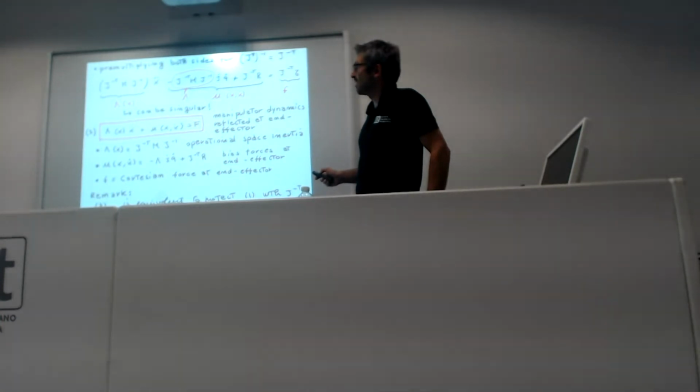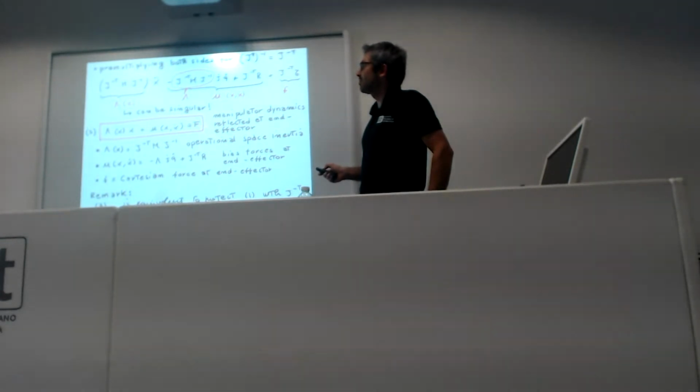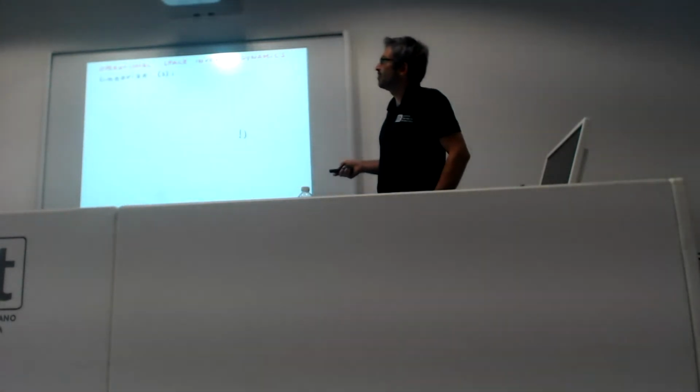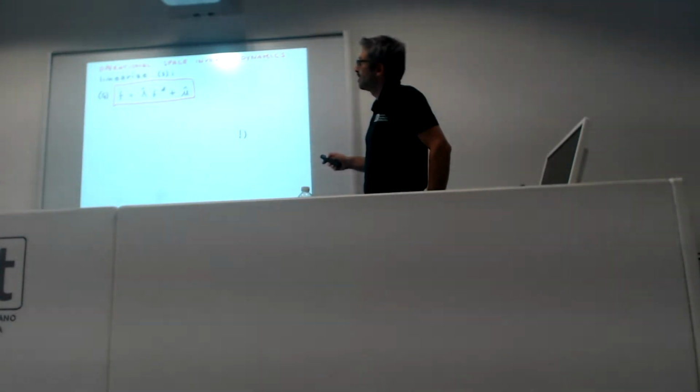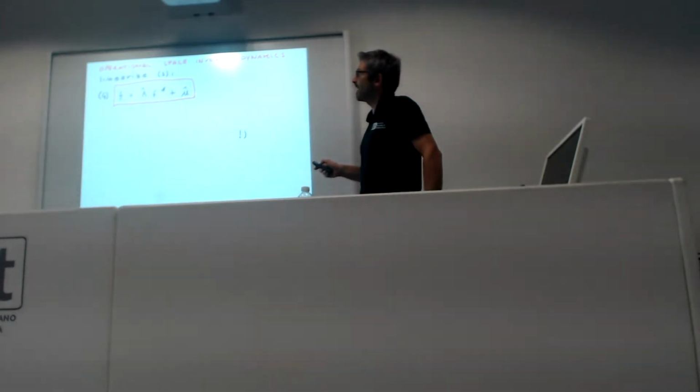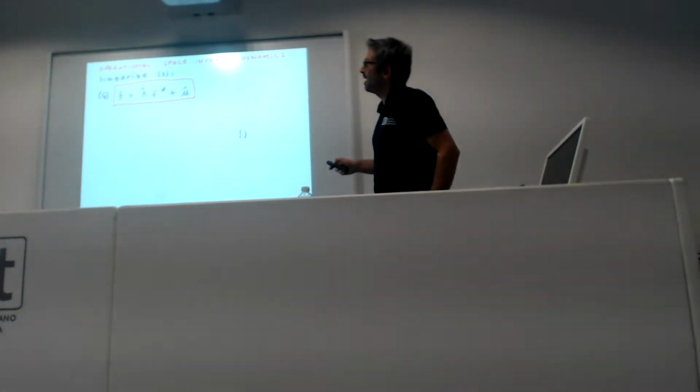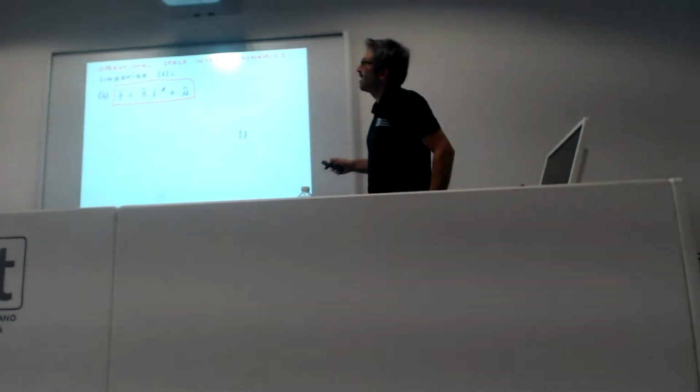So providing an input Cartesian force that contains this term and inverts this, and defines a new input. So the input force will compensate for the bias term at the end effector, and will be multiplied by an estimation of the operational space inertia.